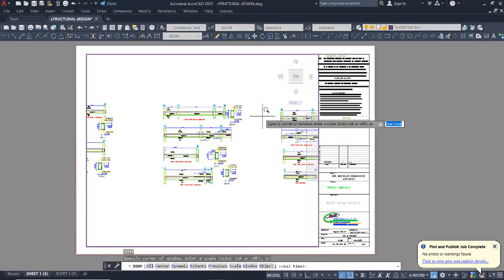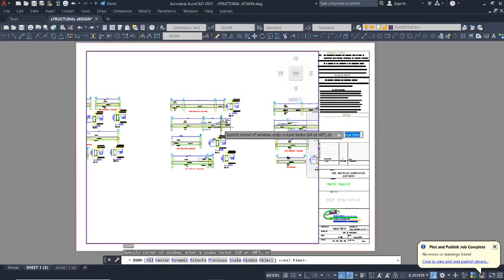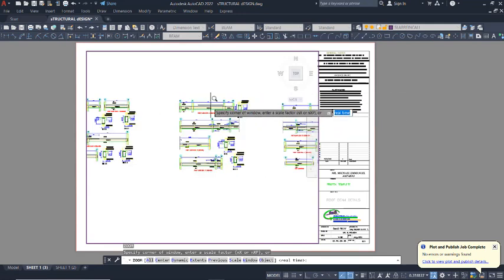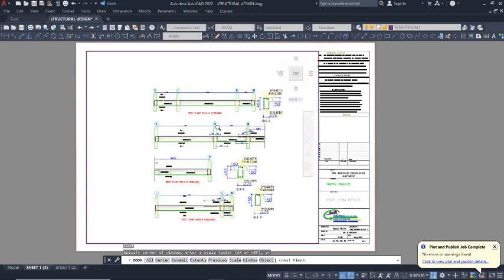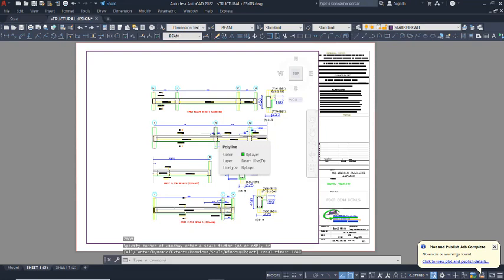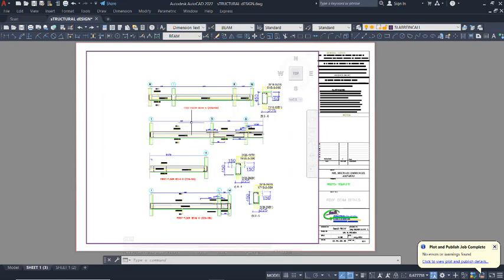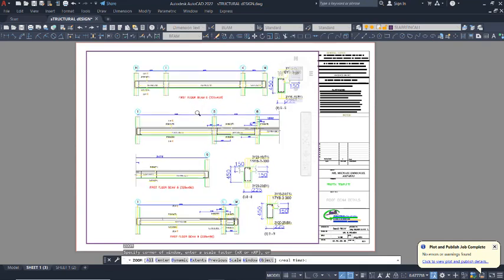After which you proceed to key in the scale at which you want to print this particular drawing facing the title block. You can use 1:40 as a scale, and then you enter. Once you enter, you can see the drawing has zoomed in, but that is not that much. So you can as well type Z on the keyboard, enter, and then key in the scale 1:30, and then enter.